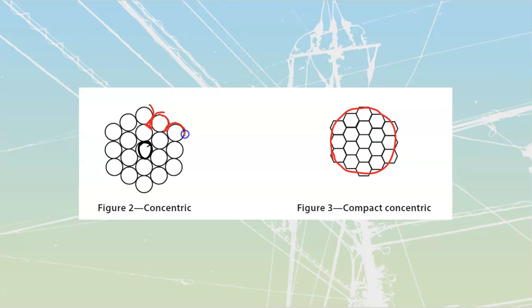So my insulation will be going around this thing. It's got all these little grabs. And as a result of all these little grabs inside of here, where it's pushing into each of those, the actual insulation will hold onto this conductor, makes it hard for us to flex it, put it into position, and makes it really hard for us to strip it. You need to be careful with these, that you pull all those little flecks out. You've got to usually do it with a knife tip or something like that.